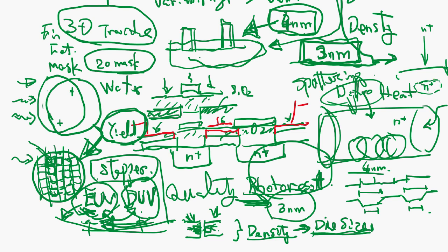So after sputtering, you do the annealing process, which means you increase the temperature and decrease slowly. Then all the broken bonds in the silicon heal. Then you make a nice N plus layer or N layer within the silicon, and you make another diffusion process this way. So this is a typical collector for a bipolar transistor. You have an embedded impurity layer. That's typically using the sputtering process.